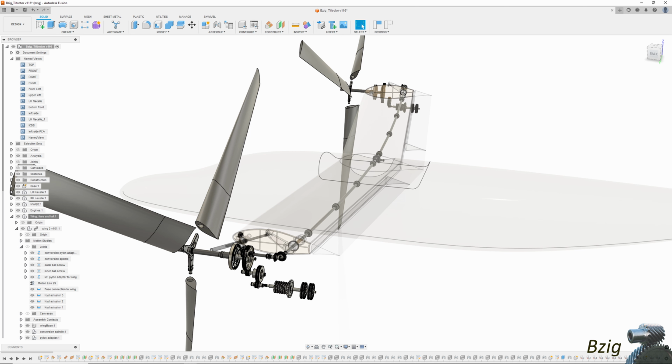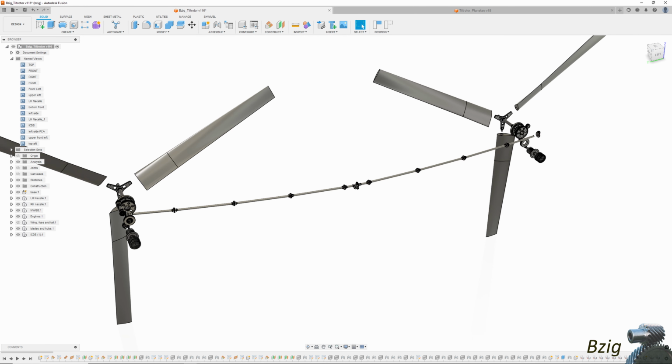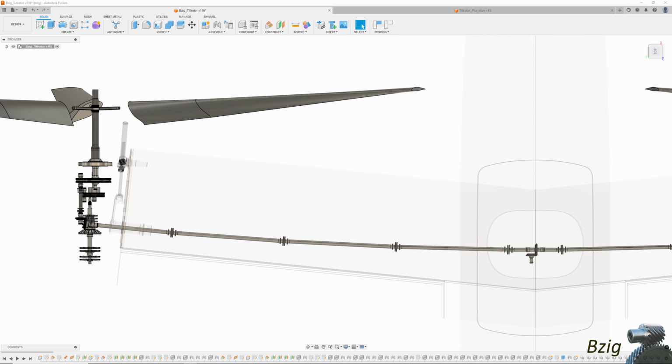But sweep and dihedral introduce a geometric challenge of passing drive power from one side of the aircraft to the other. You may think the purpose of the mid-wing gearbox is to facilitate the change in direction of the interconnect driveshaft. In fact, the gearbox did function to change direction of the driveshaft in the XV-15. But with the V-22, the mid-wing gearbox doesn't provide any direction change. Instead, its purpose is only to extract power from the drive system to power hydraulic and electric service for the aircraft.